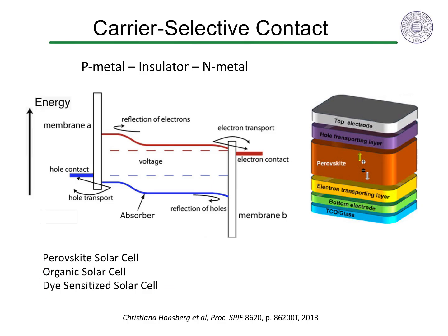The active light absorber is an intrinsic semiconductor like an insulator. Instead, these photovoltaics rely on charge carrier selective contacts, where one electrode is an electron transporting layer and the other electrode is a hole transporting layer. Ideally, the Fermi level of the metals and band alignment with the insulator are such that photo-generated electrons drift to the electron contact, while photo-generated holes drift to the hole contact. The contacts should also not accept and therefore reflect the undesired charge carrier. In this way, a high quasi-Fermi level builds up on the electron side and a low quasi-Fermi level is established on the hole side, providing the external electromotive force.